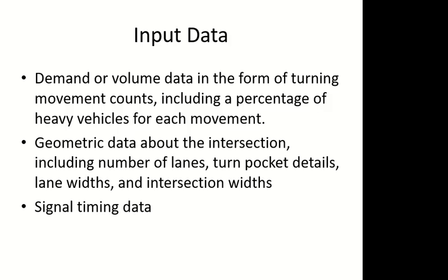Percentage of heavy vehicles is very simple. You take the total and you count the heavy vehicles separately. You can calculate the percentage. For the peak hour factor, we have to do it in intervals of 15 minutes. So you don't take 1 hour full only. You have to divide this 1 hour into 15-minute intervals. So for each direction, you will have 4 values in an hour, one for each 15 minutes. Later on, these values can be used for calculating the peak hour factor.